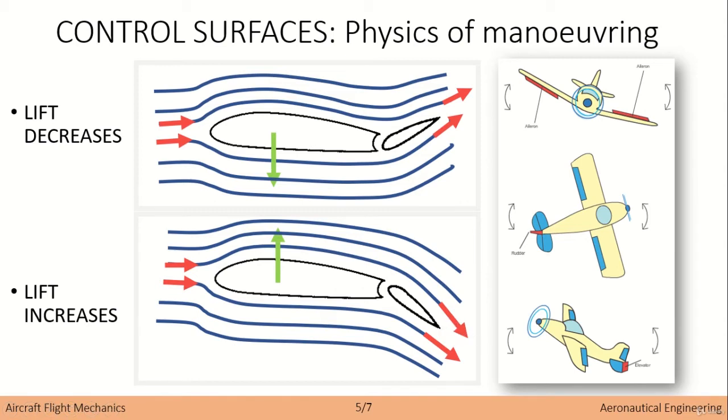Okay, so by the third law of Newton, we are able to justify that the fact that the wind is downwashed will produce a positive net force and a positive lift on the wing. Okay, so in this case we will be able to produce an increased lift just because we are moving the aileron in this direction. It actually makes sense, right?